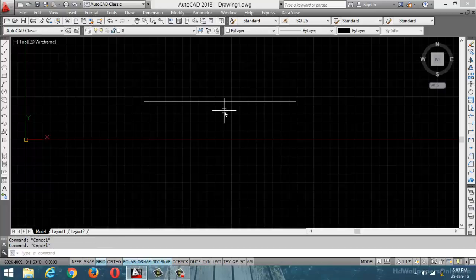Okay. Now for 2D purpose, no usage. While converting a 2D design to 3D, if you have duplicate objects, the selection procedure is difficult. For that purpose, while applying the 3D tools, first you can apply the delete duplicate object command to the entire design. Okay, that is about the delete duplicate object.